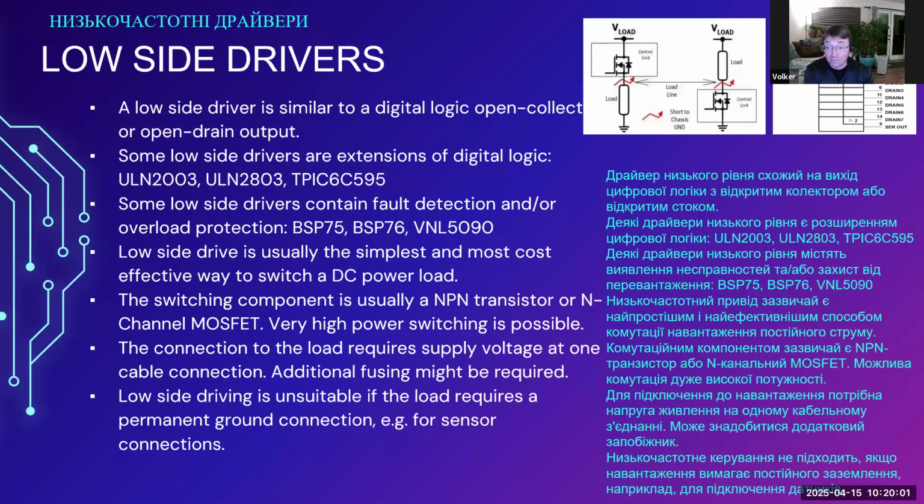And as a continuation of that, the TPIC6C595, there's a range of similar chips available. That chip in the image on the upper right-hand side is basically those two mixed together with MOSFET outputs. It is a serial shift register with parallel outputs. The outputs are low side drivers, so open drain devices, and they can switch, I think, about 100 milliamps or so, enough for a relay.